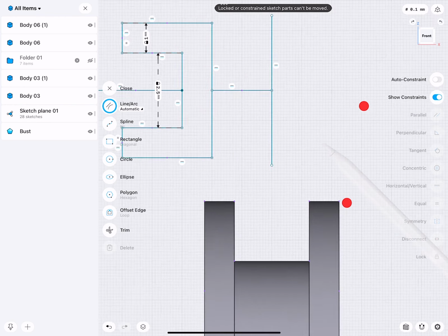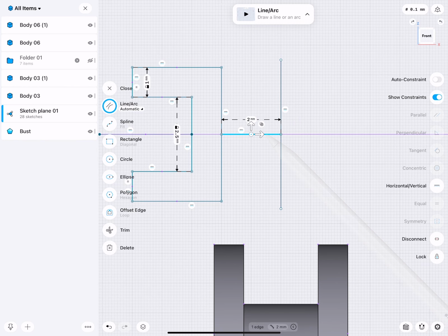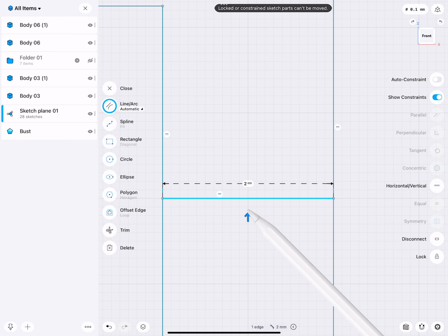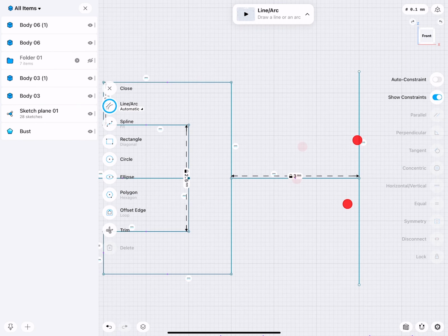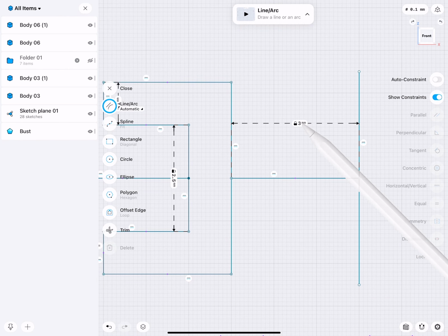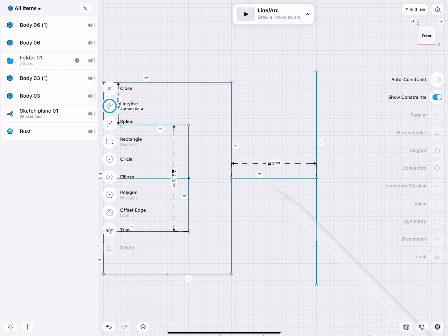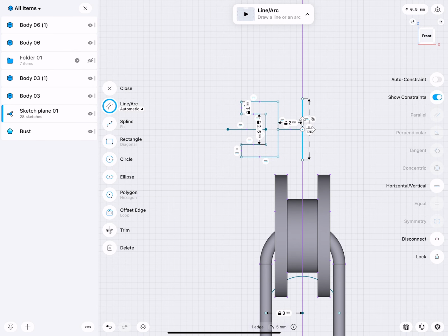With this line, I can, hold 1 second. There. Adjust actually the radius. So this way I have a controlled means to figure out where is the center for the revolve object.